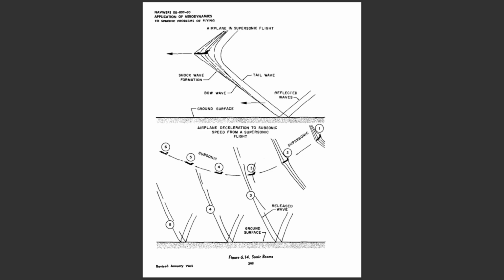When the airplane is in supersonic flight, the local pressure and velocity changes on the airplane surfaces are coincident with the formation of shock waves. The pressure jump through the shock waves in the immediate vicinity of the airplane surfaces is determined by the local flow changes at these surfaces. Of course, the strength of the shock waves and the pressure jump through the wave decreases rapidly with distance away from the airplane. While the pressure jump through the shock wave decreases with distance away from the surface, it does not disappear completely, and a measurable but very small pressure will exist at a considerable distance from the airplane.